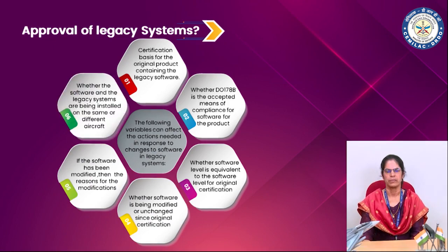Gracie, now that we know the types of legacy systems, how do you go about certifying these legacy systems? The following aspects are to be considered for certification. Certification basis for the original product containing the legacy software is available. DO178B is accepted means for compliance for software for the product. Software level is equivalent to the level for which original certification is done. Whether the software is being modified or changed since the original certification.